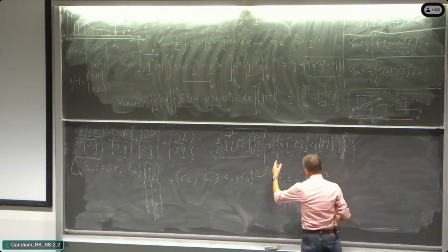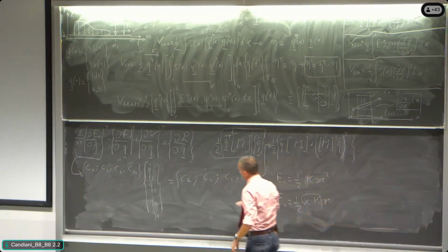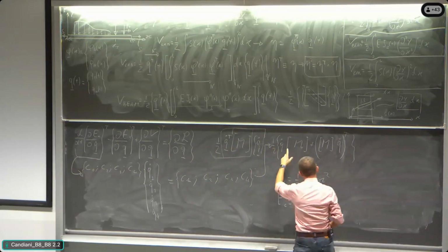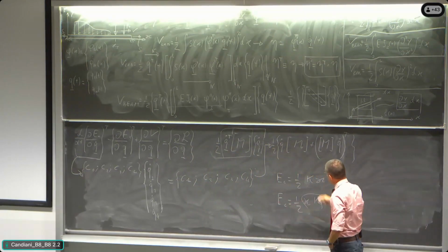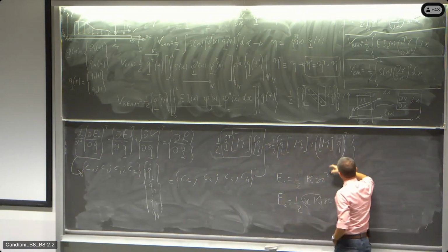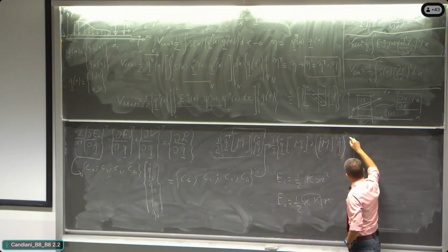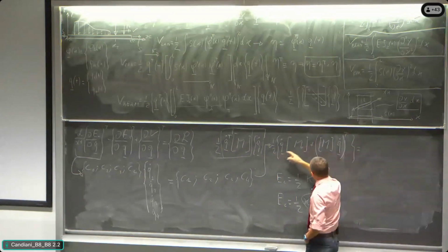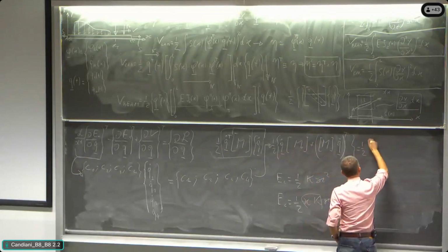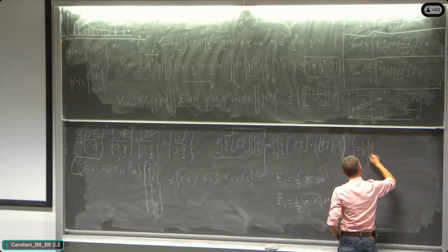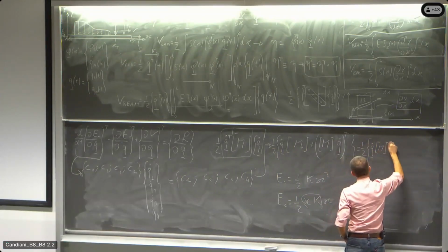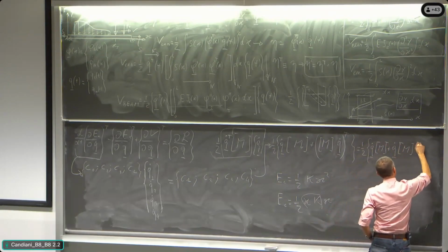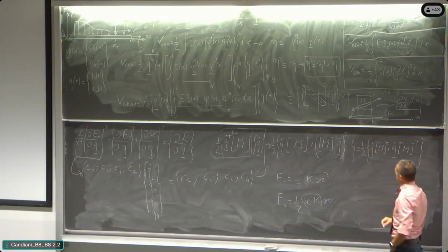And so finally, the derivative of this quantity here, with respect of q dot, is 1/2 of q dot mass matrix plus mass matrix q dot transposed, that is equal to 1/2 of q dot mass matrix plus q dot mass matrix transposed. All right.